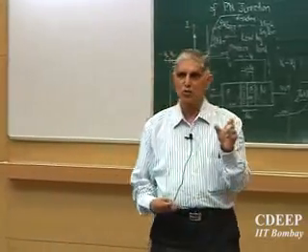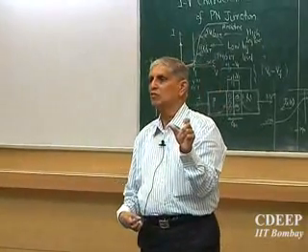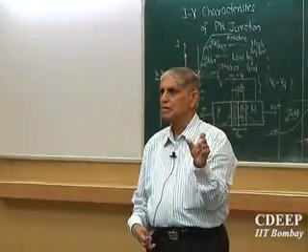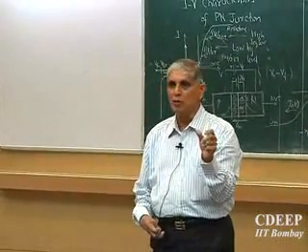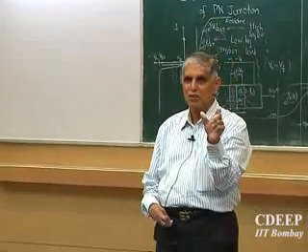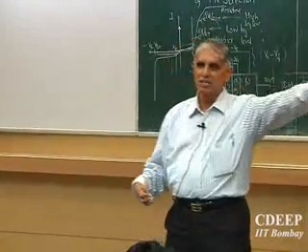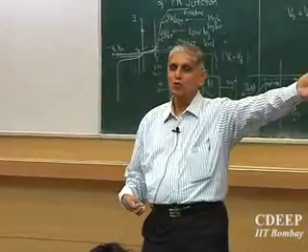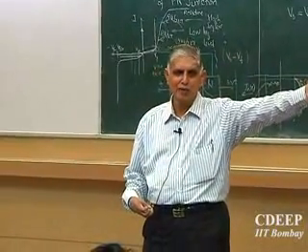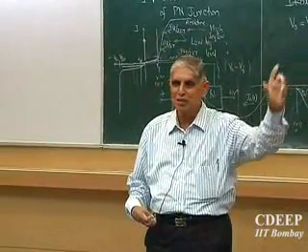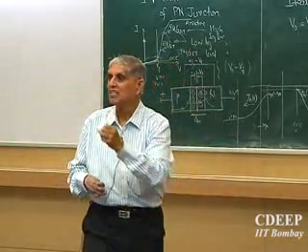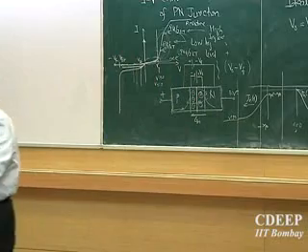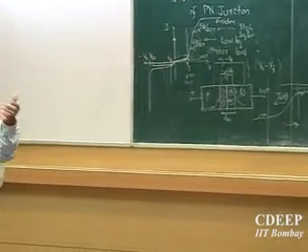If there is charge neutrality, what is the electric field there? The electric field is 0. That's what we say, charge neutral. However, if there is charge neutrality, how do these carriers reach the contacts? So there must be some electric field in the P region as well as in the remainder of the N region, which will take these carriers to their logical end, the contact.